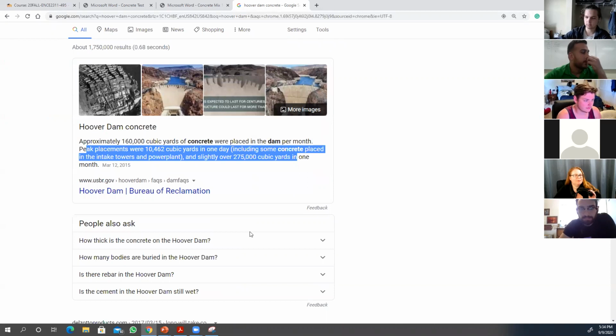I don't want to get into too much, but there was one instance where they tried to reduce the temperature, because temperature is important. At this scale, it might explode. Imagine that this dam explodes. What they did was they used pipes, and through these pipes they were not giving water into the concrete, but the pipes were cooling down the concrete. And at the end of the curing time, they filled the pipes with concrete. They took the pipes and filled them to reduce the temperature. Imagine, it's important.